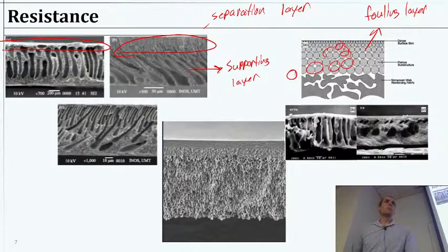There are a few cases where people actually design a membrane such that it accumulates some fouling stuff and then uses that fouling layer to do the filtration. That's not very common. Usually we're trying to avoid fouling and shake it off, wash it off, backwash it. And membranes, if we backwash, which most of them do, it's a very quick, small spurt. We just reverse the flow for a moment and shake everything off that we can, and might go a 10-second or 20-second backwashing cycle in every minute of operation, or every 10 minutes of operation, something like that. So depending on the design, depending on the scheme, that's going to change a fair bit.